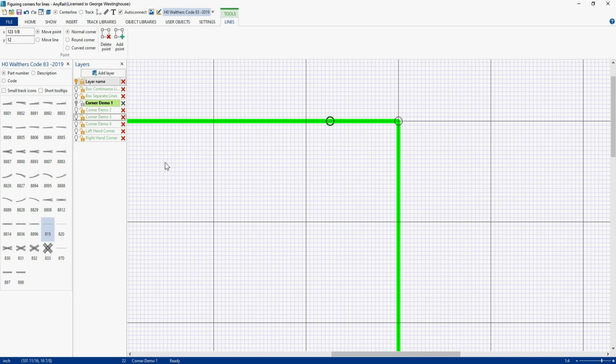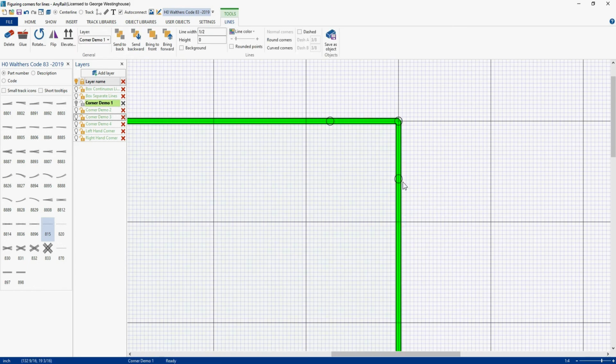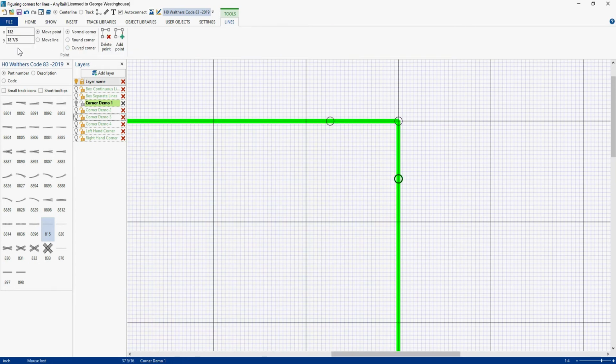So when you're working backwards like this, you have to subtract. When you're going from left to right, you're adding. When you're going right to left, you're subtracting. Same thing in the vertical. If I'm going this way, I'm adding to this point. At the bottom of the drawing, we're going to be going up this way, so we'll be subtracting from the point. So let's put in our point here, and its Y is going to be 20.875.